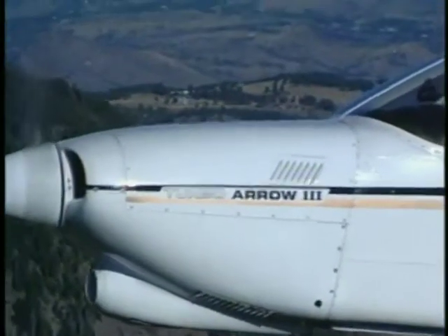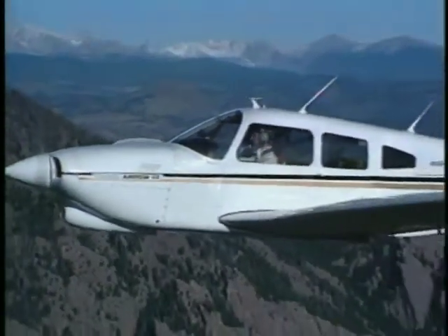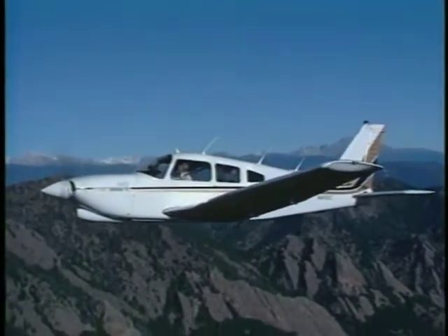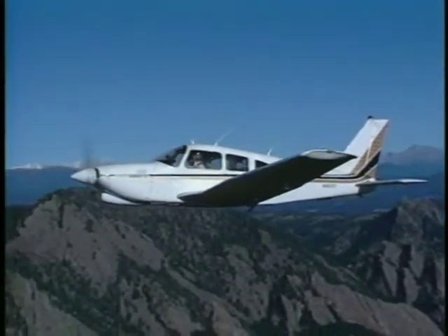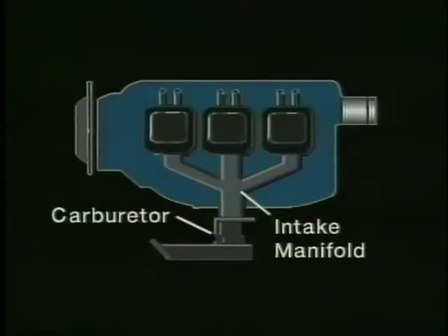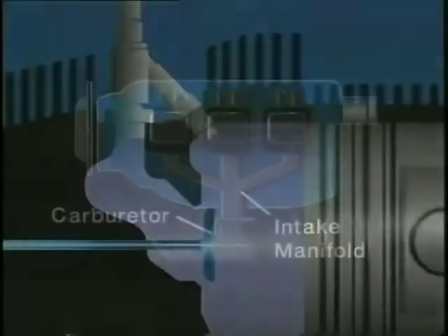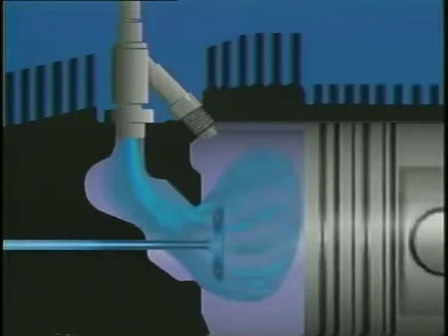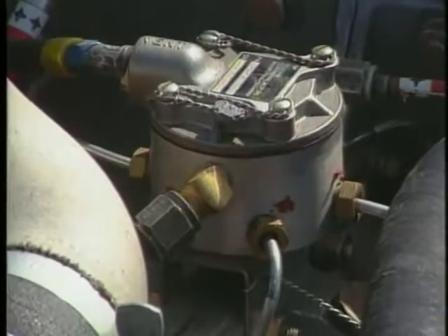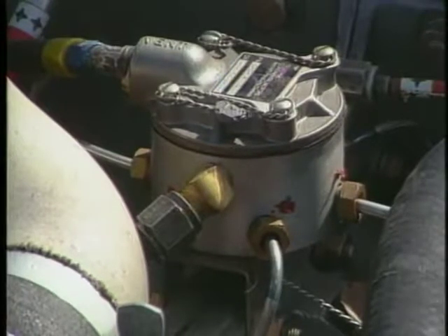In an effort to gain the maximum amount of power from small lightweight aircraft engines, manufacturers have devoted a great deal of engineering research to advanced fuel induction systems. One of the most successful of these is fuel injection. Unlike a carburetor, which mixes fuel and air prior to reaching the intake manifold, a fuel injection system injects fuel into the intake port, where it is mixed with air just prior to entering the cylinder. This allows for an even distribution of fuel to the cylinders and a more uniform mixing of the fuel and air.